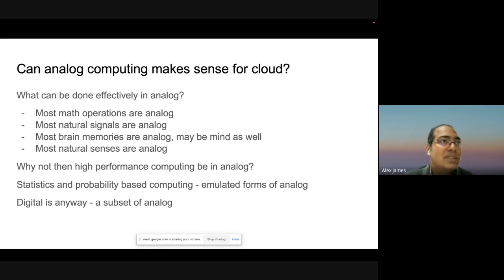there's nothing stopping us from doing it, but the question is, will it be accurate? Many times, when you want to do a mathematical computation and use an analog processor to do this, the challenge is that some errors may come because of parasitics, or because of the way in which the circuit or the chip itself is designed, the EMI issues and all those things that come by.